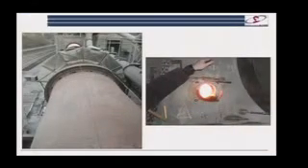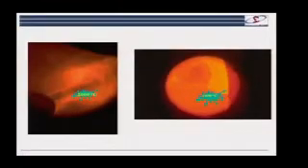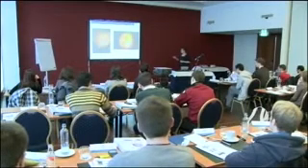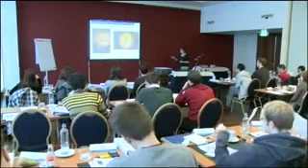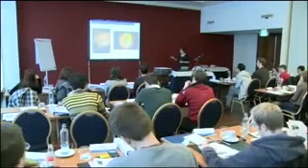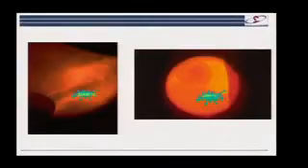It comes down to the flame. So this is now your flame. And your flame has a temperature of about 2,000 degrees. And the hottest part of the kiln, the clinker, the raw meal, this is the raw meal here, you see it's coming down here. This goes up to 1450. Now, these temperatures are quite important.